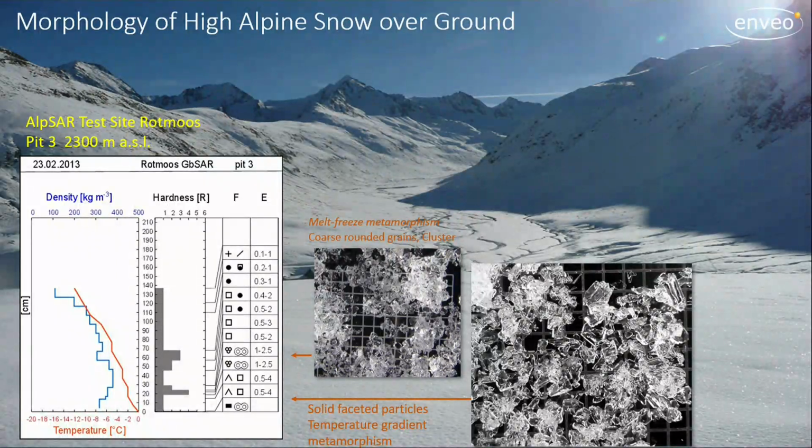And this is the reason why we are also measuring the temperature profile in the snow pit, every 10, 15, or 20 centimeters. Close to the ground, in this case, we have 0 degrees, because we have thermal insulation and the geothermal energy is going up and heating up the ground-snow interface. Closer to the atmosphere, we are mainly influenced by the weather conditions, so by the snow.